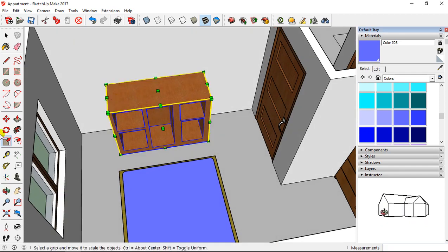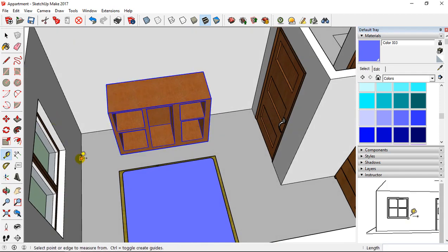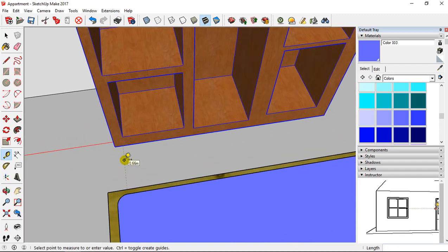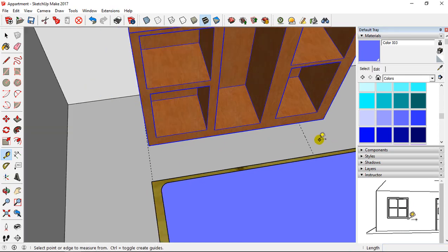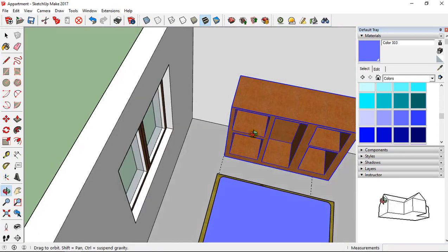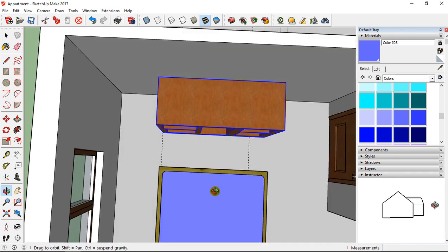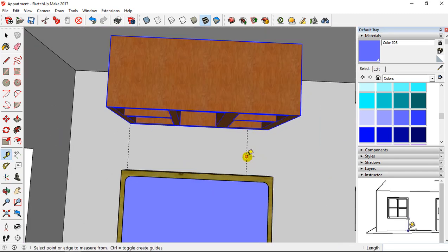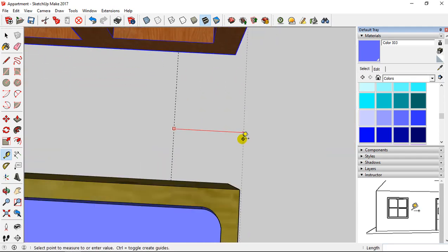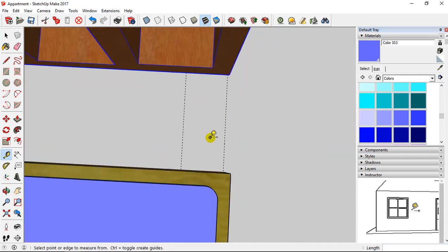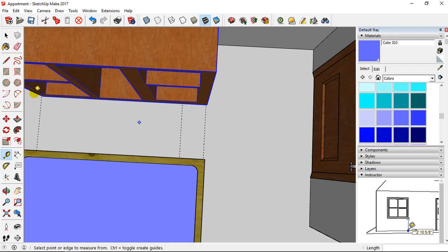If I want to have the right dimension, I add a guide, so I can add a guide here at, for example, 60 centimeters. Then I can take a guide also, and I'm going to add one at 120 centimeters. But 100 centimeters, I'm not totally near this place, so I'm going to do exactly the same and go 20 centimeters to arrive exactly in front of the bed.